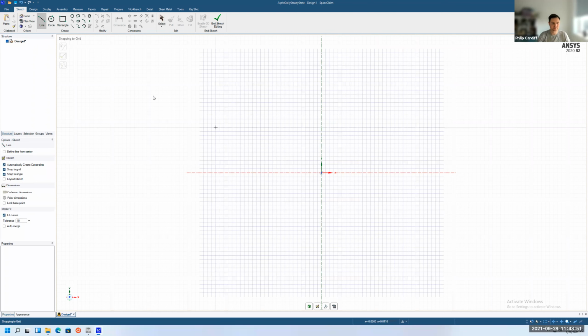Okay, I'm going to draw a line. We can either click and hold and drag, or I can just click the first point and then click the center point. Before clicking the center point, you can see it is actually letting me type a distance. In this case, the first line is 0.0206 meters. And press enter.